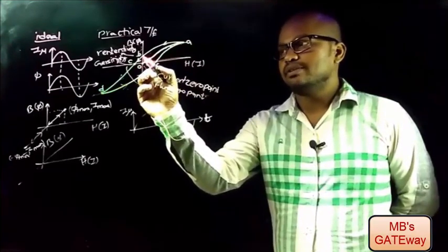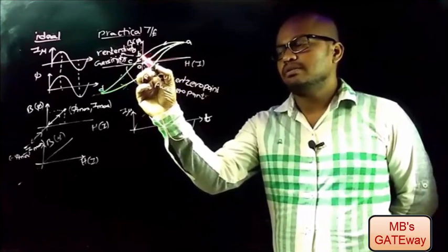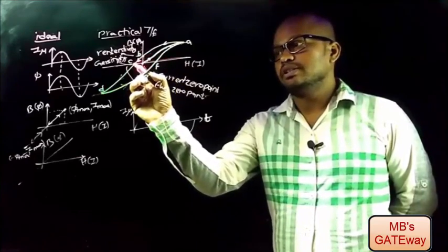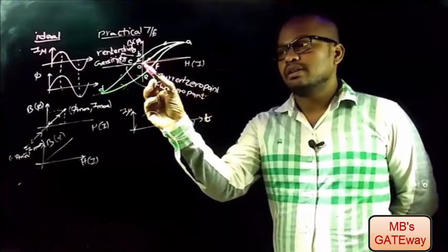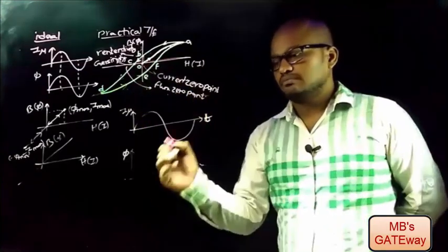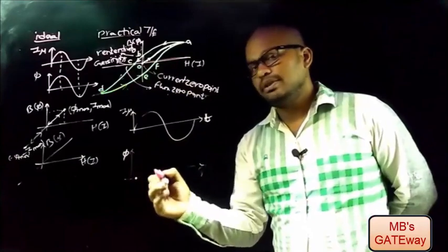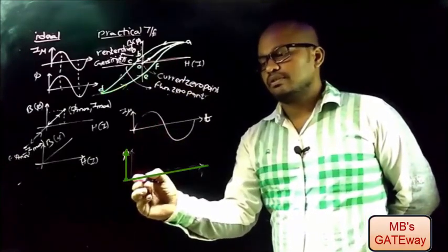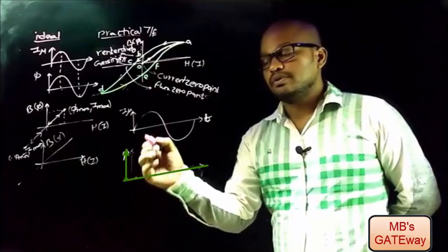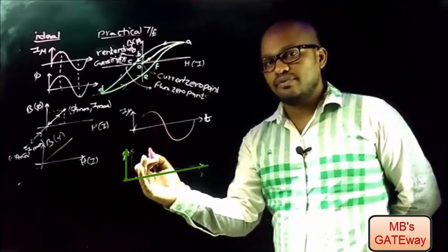And then with reversal magnetism, the curve will trace the path B to C, and this point C represents the flux 0 point, which means that current leads the flux, means the flux 0 point will be here and the current 0 point will be leading, which means that current I leads and flux phi lags.